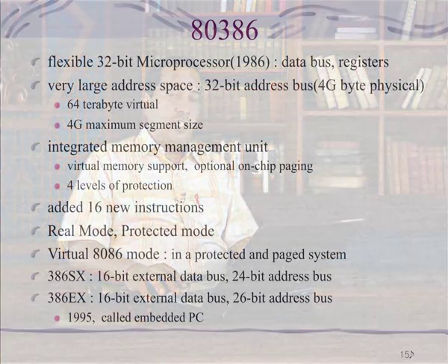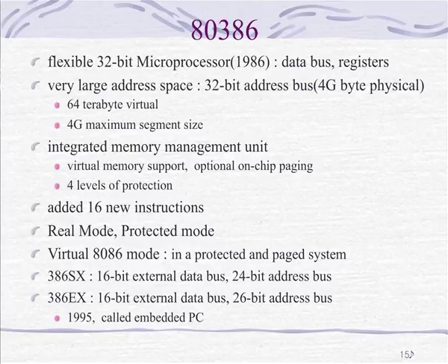So, what is done is that this whole program of 1 kilobyte is divided into segments of 256 bytes, and at a time one segment is executed, and once the segment is executed, this segment is removed and the next segment is brought for execution. So, for the user it seems that a bigger program has been executed using a smaller memory. This is the virtual memory concept. This feature was available in 80386.